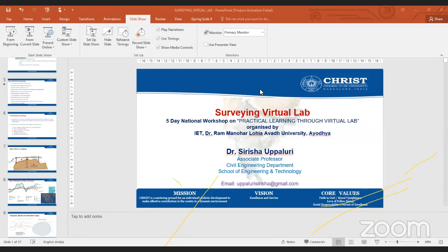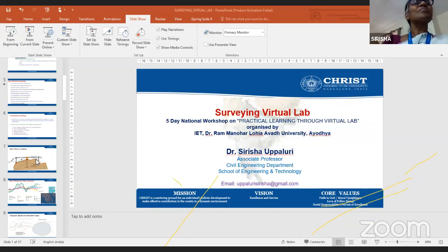Okay. Is it okay, Shreyas? Which slide? Always the level surface, the mean sea level, is curvilinear in nature. If I am drawing a plane on the level surface, then the level plane will be tangential to the level surface.